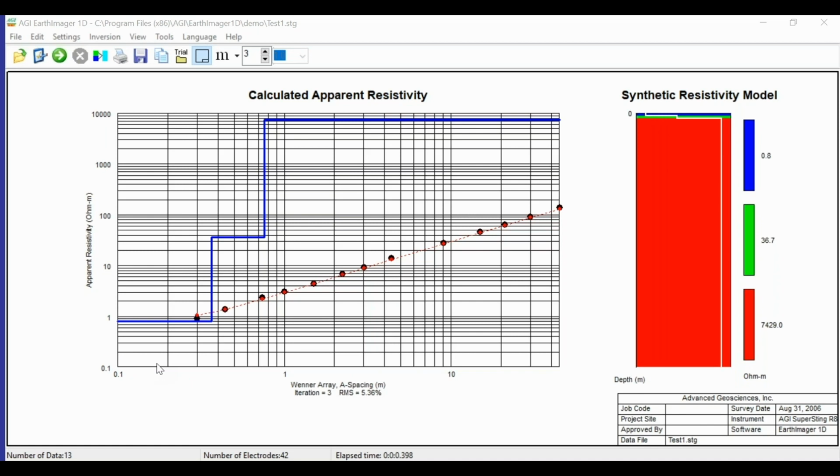If you're using maybe 1 meter electrode spacing, then you're not going to put in 40 centimeters. You just need to put in about 10 to 15% of that distance, like 10 to 15 centimeters for 1 meter electrode spacing. If you have a 10-meter electrode spacing, then in that case, you can put 40 centimeters all the way down. That will create a better contact with the ground.